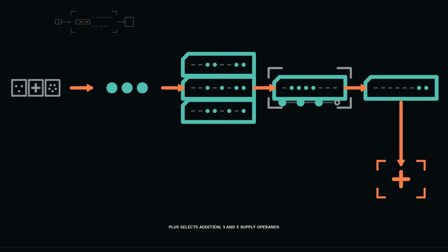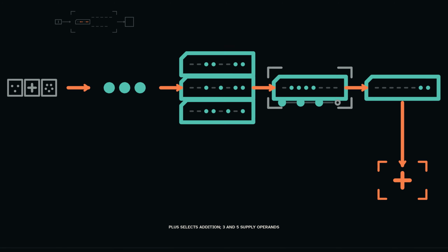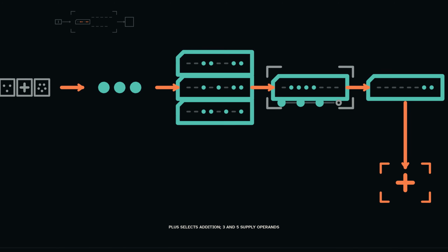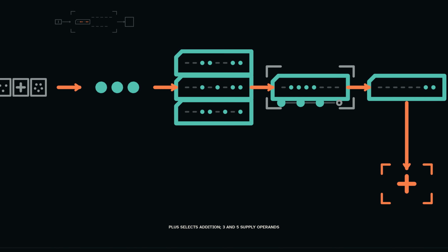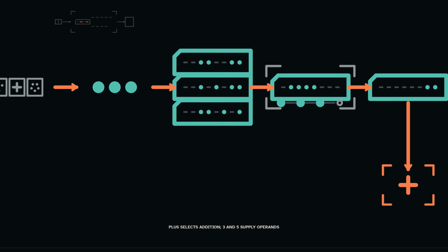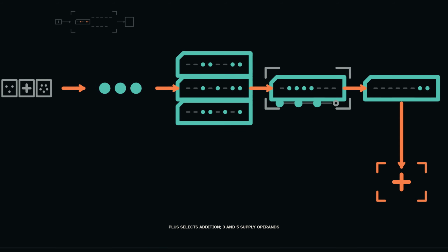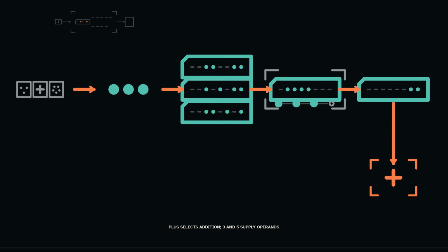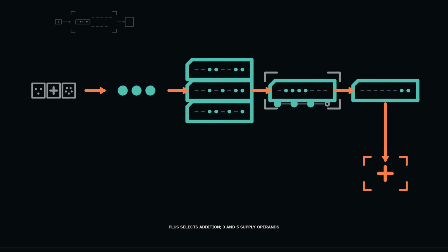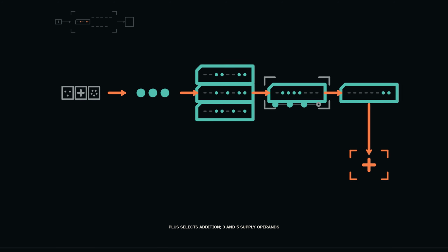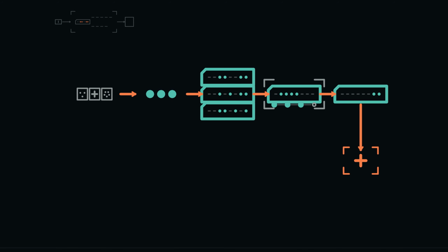The second data load consumes hexadecimal 2B into R2. A compare instruction checks it against the program's supported plus code. Equality sets the 0 flag, so the following conditional branch selects the addition path. This is where the operator input has causal force. The controller does not add because the diagram displays a plus sign. It adds because the entered operator byte matched the declared code and the branch followed the corresponding stored instruction route.